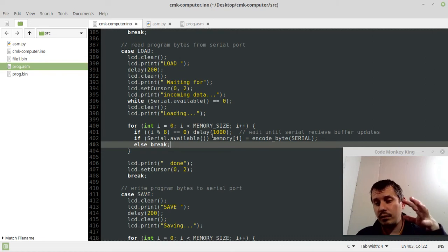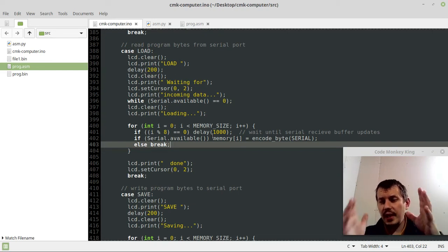And on the hardware level, what happens is on the receiving side, the buffer takes up to 8 bytes, and when it gets full, the next byte that comes in automatically clears the buffer, and the new chunk arrives if it's already available.